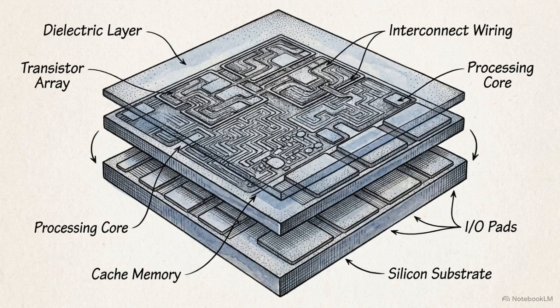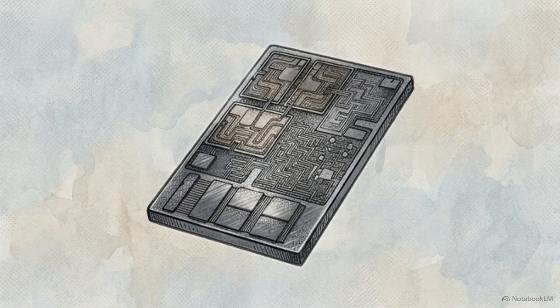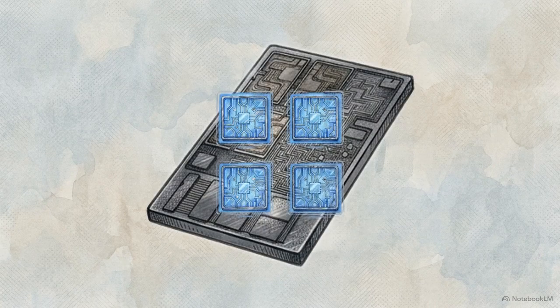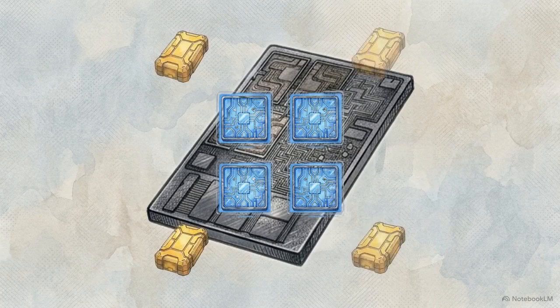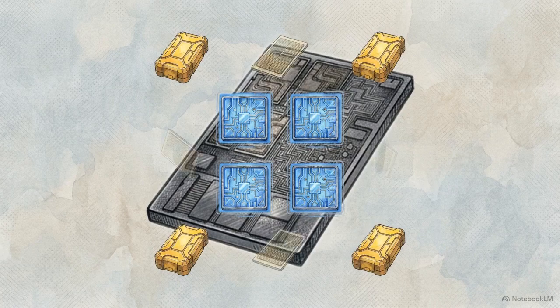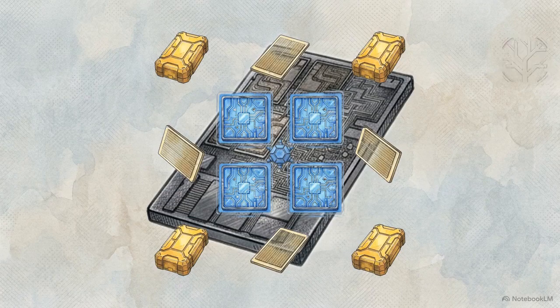The capabilities of these processors are dictated by the physical layout of their silicon dies. This CPU die contains a small number of execution cores, typically 4 to 8. These units are large, sophisticated, and powerful. However, they occupy only a portion of the chip. Large blocks of silicon are dedicated to intricate control logic and local memory caches. This control logic is essential for managing complex sequential paths. It allows the CPU to perform branch prediction and reorder instructions to keep irregular software tasks moving efficiently.